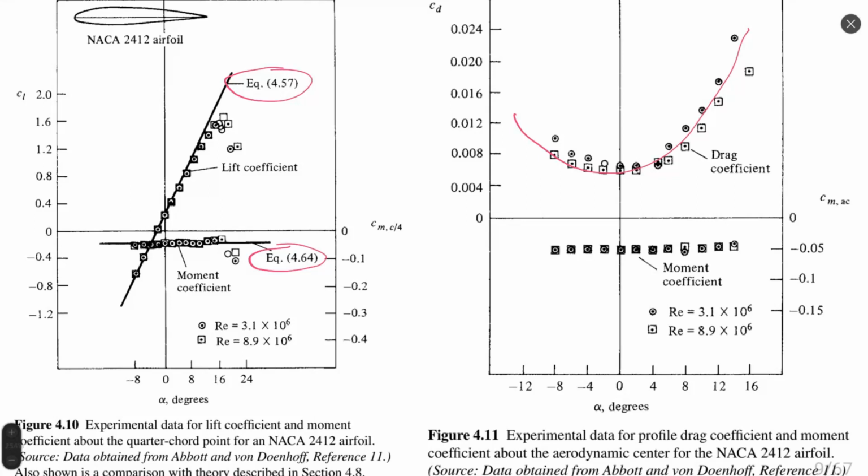So this must be very clear to understand: analytical methods are not so powerful and not possible to use for all cases, especially in the case of drag. Drag on an airfoil is mostly formed by viscosity and the boundary layer, the flow interacting through the boundary layer with the airfoil, and such interaction is so complex that it is not possible to describe it by any analytical formula.